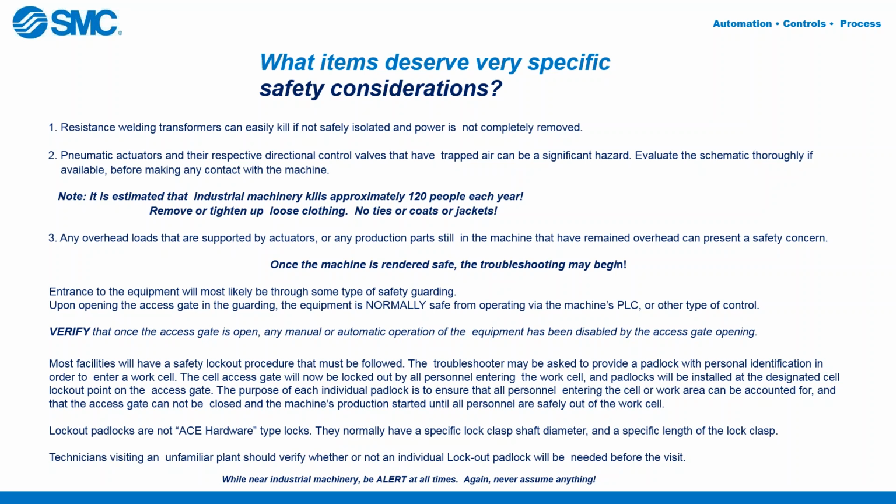I know years ago I got yelled at by a maintenance tech. I pressed a manual override on the valve, and about 40 feet away, he was looking at something, and the cylinder moved, and he wasn't close enough to be hurt, but he was a little scared, and the language he used was even scarier. So be careful about those kinds of things as well. Manual overrides can be troublesome, especially if there are other people assisting you.